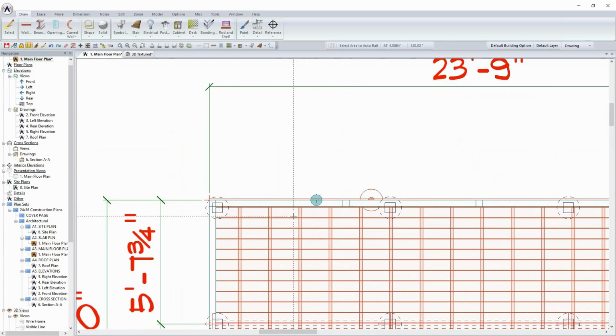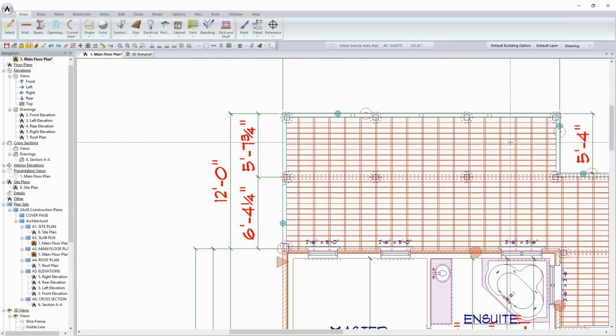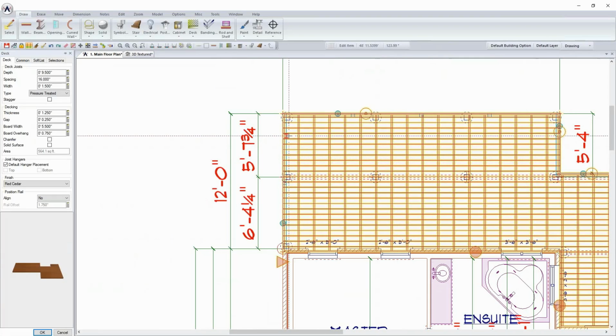And the railing itself, when you apply it, it's going to have these reference circles assigned to it, which attaches it to the edge. Now, the placement of the railing itself, if you do a right click and you do an edit on the deck, when you edit this deck, it's pulling up the dimensions on the actual deck itself, but you will notice that the railings can also be aligned or positioned relative to the deck themselves. Currently, right now, there is no positioning of it, and so I can come in at this stage now, and with the align set, I can choose to center it on the ring joist. I can move it to the outside, or even move the rail inside.